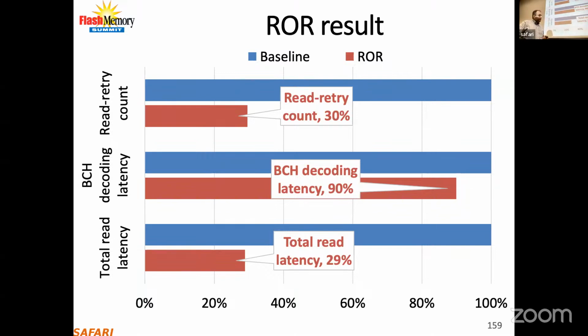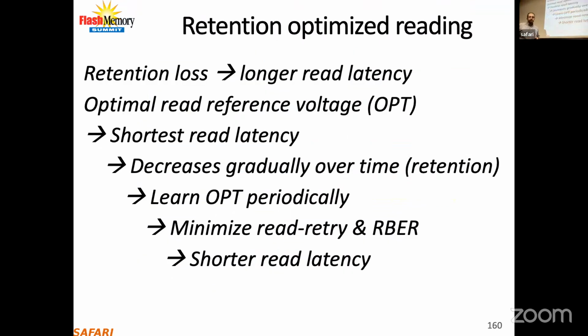This is not very important for new files. Those files that are new probably don't have a lot of retention errors, and this technique is not for them. But for data or files that have a long retention time, which we call old, you're going to have a lot of read retry, and the performance for them is quite low. So by this technique, you can at least provide some better performance.